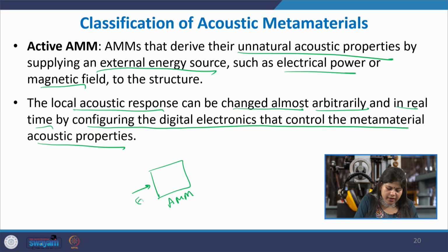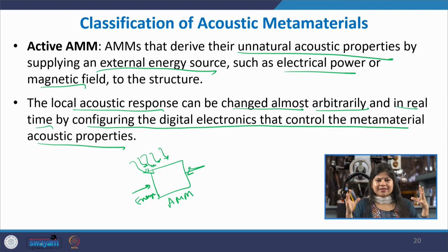and some energy source, and when the sound wave is hitting, depending on the frequency content of the sound wave, the external energy can be used to either increase or decrease the spacing of the unit cells or the various geometry, and do an adaptive noise control, changing the properties of the acoustic metamaterial in real time.